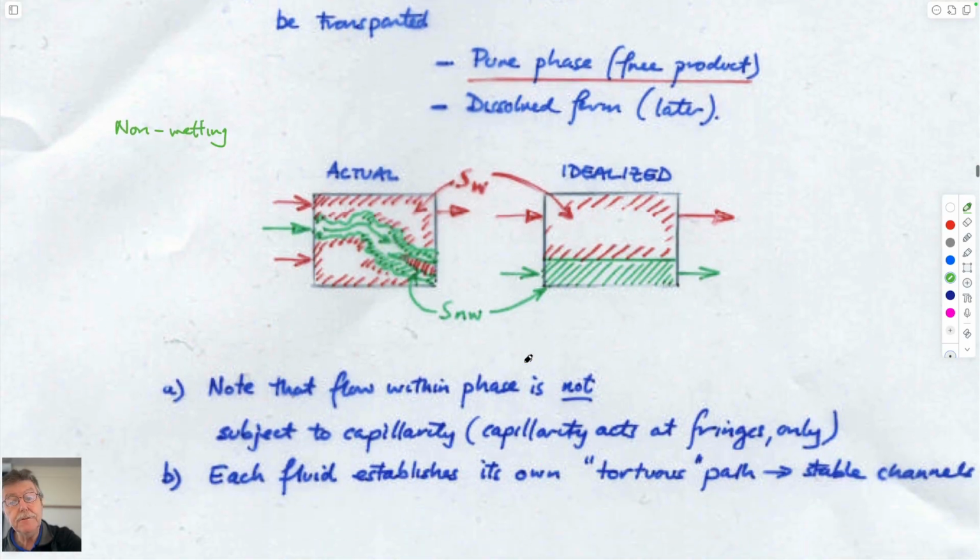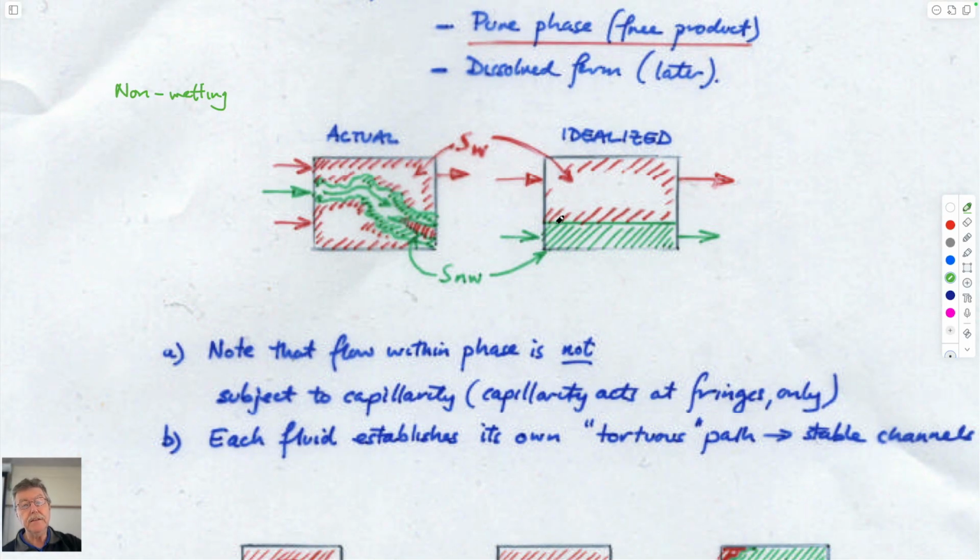They have an interface between them. This interface will allow capillary behavior to operate, where surface tension of the two fluids and the grains that contain those fluids separate them from each other. And capillary forces tend to be very strong, but away from this boundary, they don't have any relevance on the flow whatsoever. They just maintain this boundary.